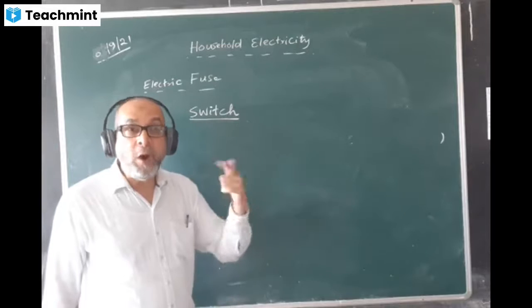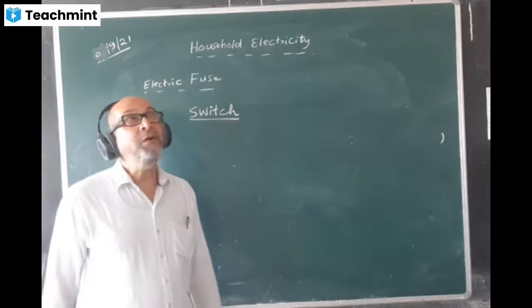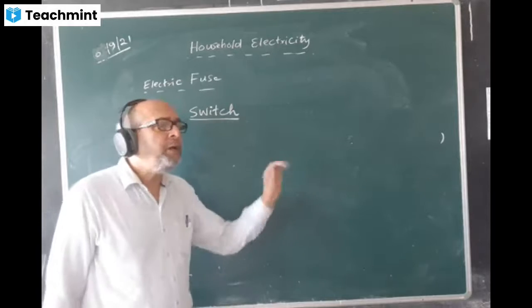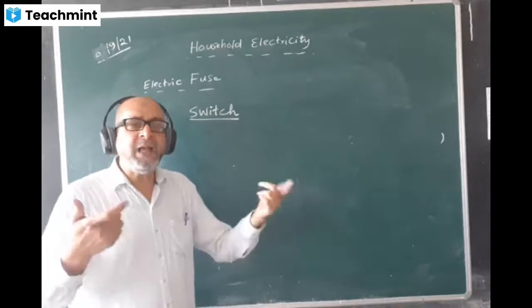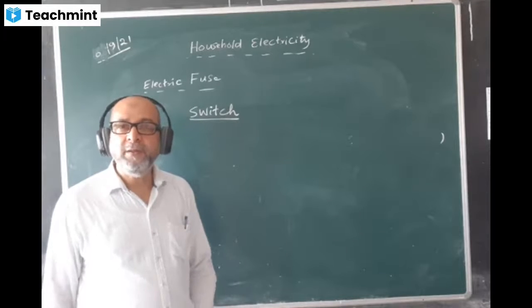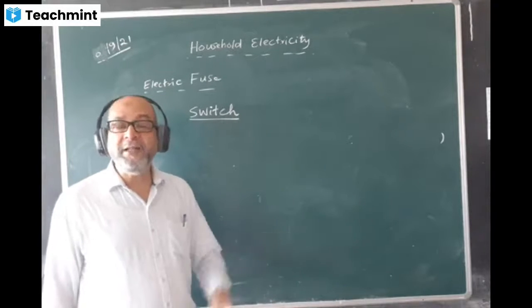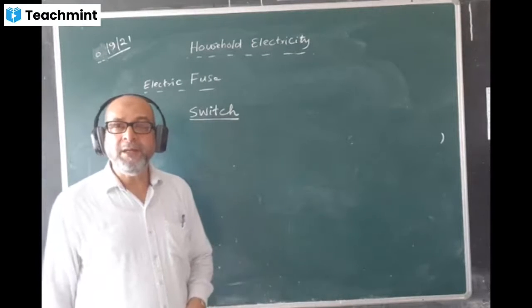You are switching on and you are having the fan working. And you don't want the fan to be working, you put it off. So as per your requirement and as per your desire, the switch is an on-off device. And as I told you, it is always connected in series with the live wire only, nowhere else.